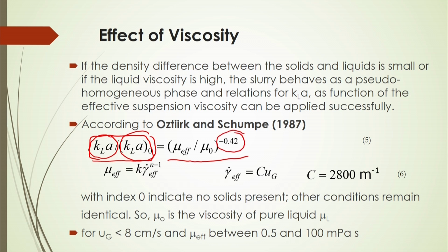So, it is seen that in the presence of solid particles, the mass transfer coefficient decreases with a power of minus 0.42. And this mu effective means effective viscosity.